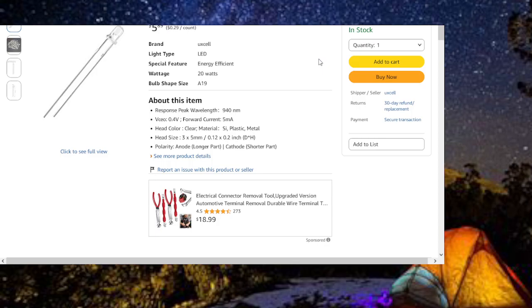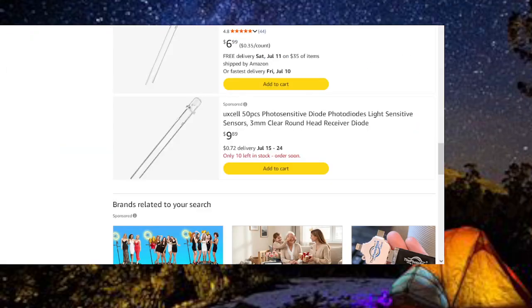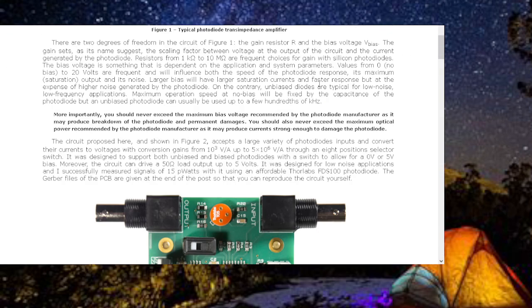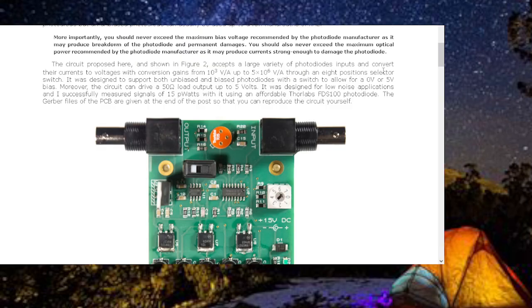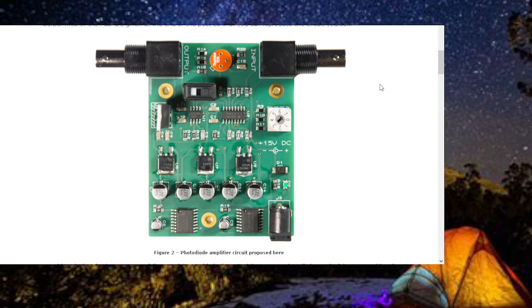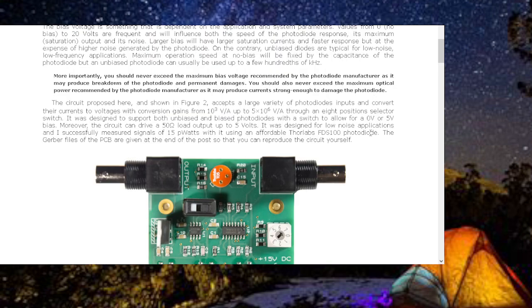$940. Now, see, you got a circuit like this, okay? This is a severe problem with the work that I'm trying to do. You cannot have this, because you've got so much stray capacitance, inductance, resistance, everything in here that generates this noise. You just cannot have it.